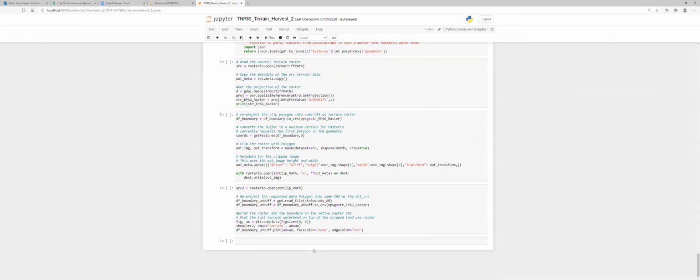You don't have to manage multiple tiles, and you don't even have to figure out which tiles you need to download, right? Because the service will do that for you. So you just say, hey, I need this polygon, and it goes, cool, what's the shapefile? You give it the shapefile, and it goes, oh, I'm in Central Texas State Plane, okay, reproject that to TNRIS's statewide service, overlay it and intersect it, figure out the tiles that you need, download them, unzip them, merge them, and then barf it back as one DEM file. It's really silly that I've had to write this, but it's super helpful once you get into the mode of what you're doing.